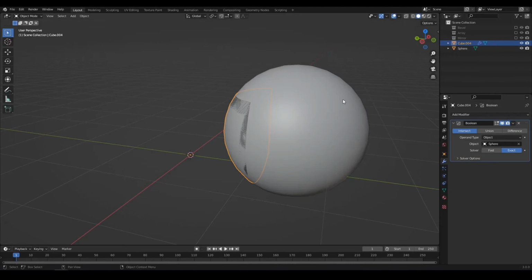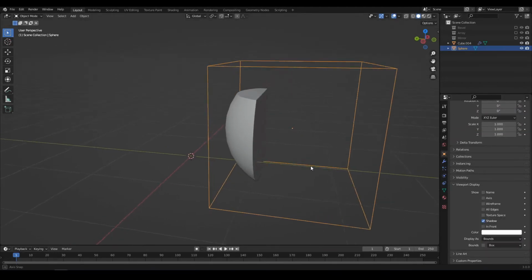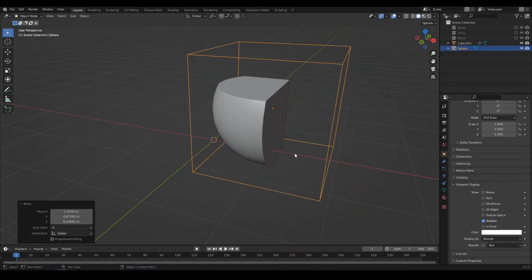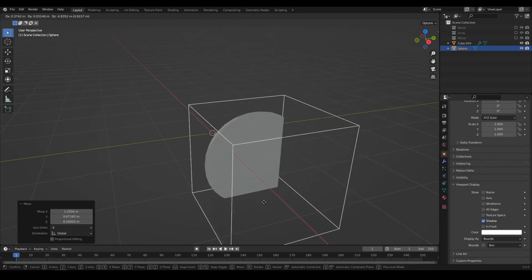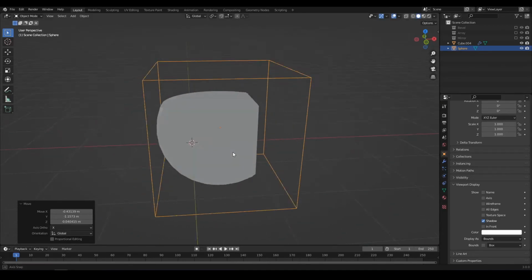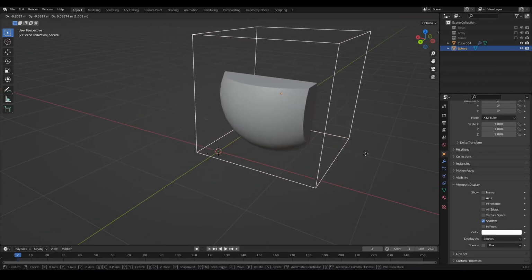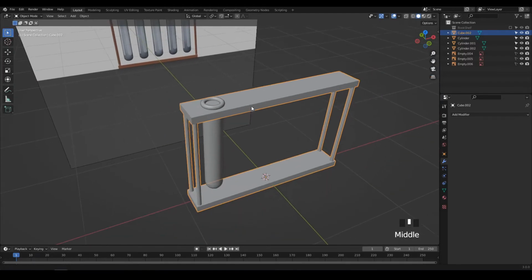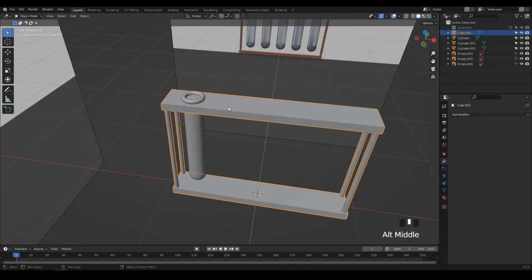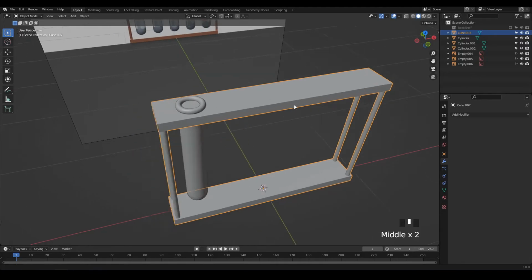Again, if I select this sphere, switch back to bounce and move it, you can see I have the possibility to affect my objects in real time as many times as I want, and to change the settings like that. Okay, so knowing that, you understand that what we want to do here is create holes in these test tube supports so that we can fit the tubes here.